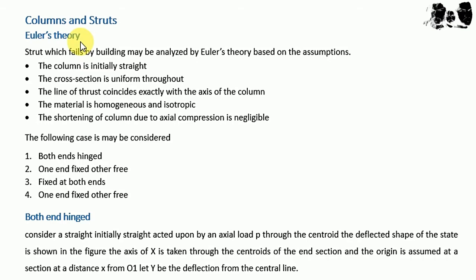Also in a steel structure, the first thing that comes to mind is bridges, where we have diagonal members, on one side or two sides, which work as a cross-diagonal structure needed to transfer lateral loads or give lateral stability to the structure.